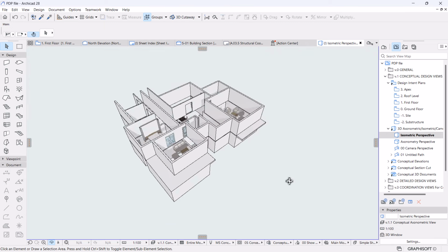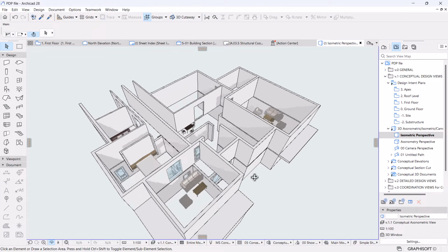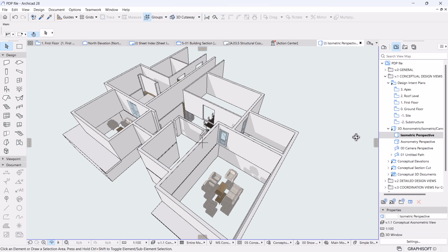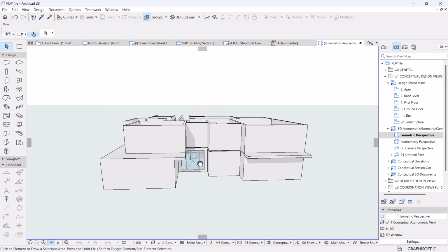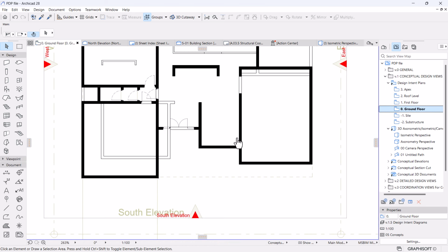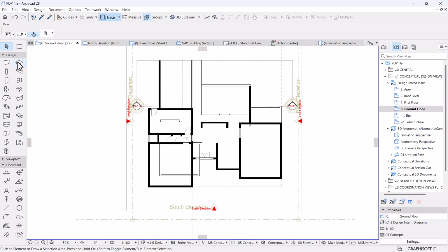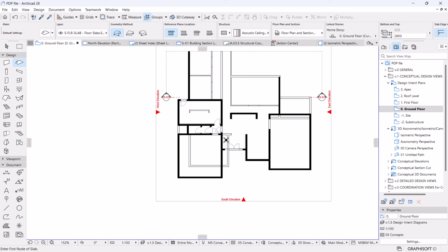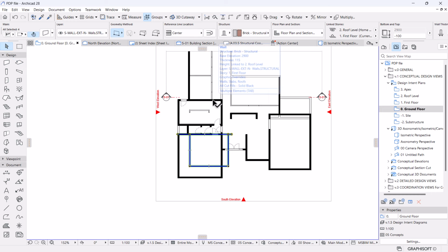So in order for me to be efficient, I need to place all the slabs first, and then I can think of how elements are going to be added within our facade planes. So let's go to the ground and activate the slab tool. Let's switch off the trace reference. We have this wall. I don't think it's supposed to be showing on our floor plan.